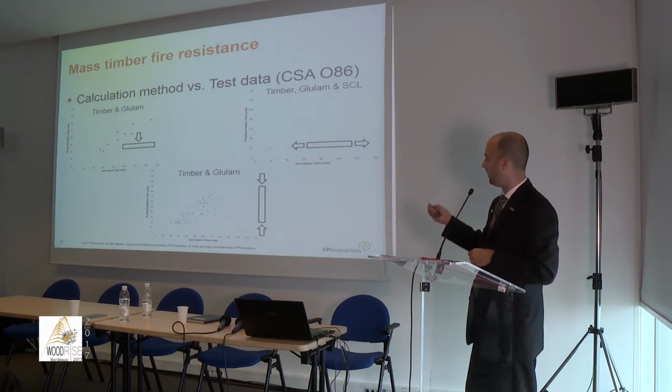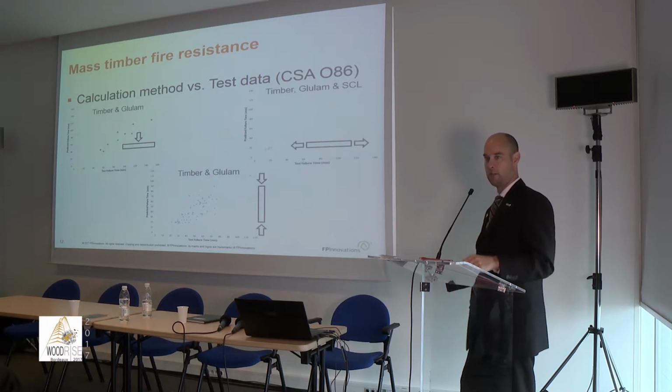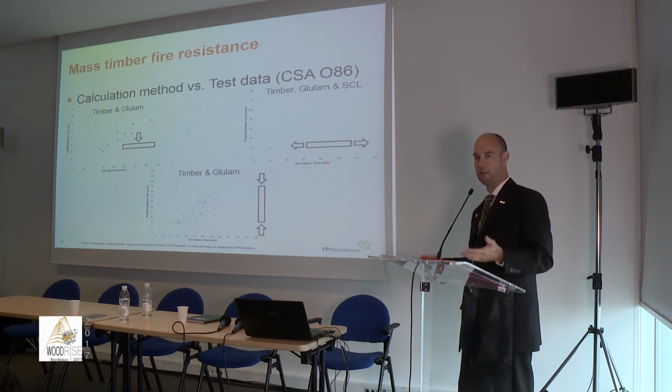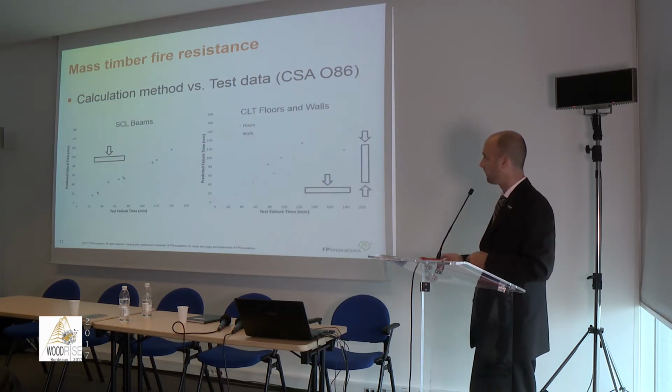When subjected to tension, it's more accurate. And then if you have columns, you have a greater variability because of the end fixity, but otherwise you see that the calculation method usually predicts well and slightly underneath what you would actually have through a test.